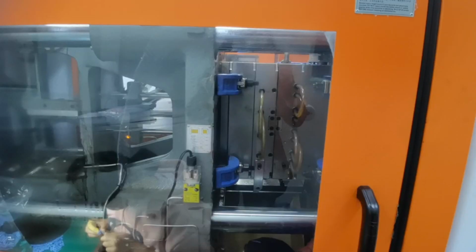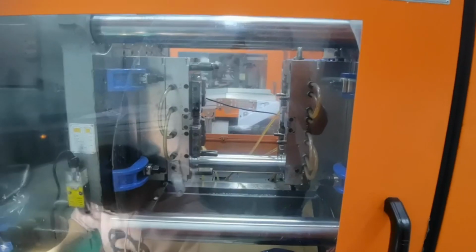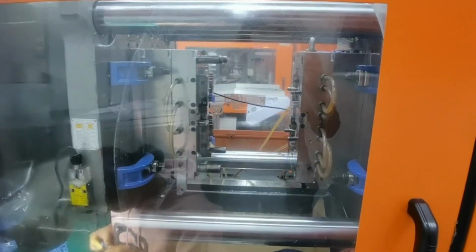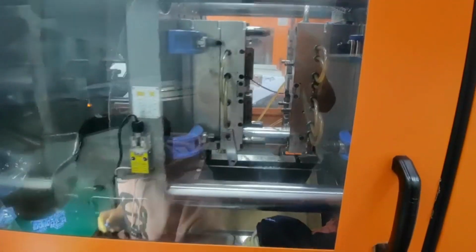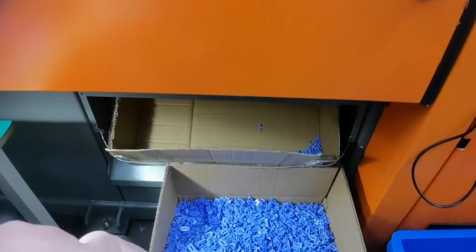Modern injection molding machines can regulate the holding pressure and time by means of a precise control system. During the holding pressure phase, the screw advances slowly according to the set parameters to replenish a small amount of plastic melt into the cavity until the end of the holding pressure time.